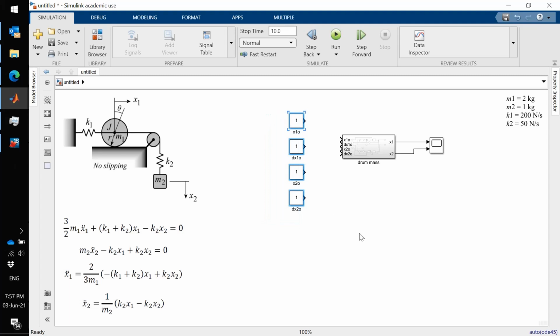You can select all blocks here, press Control button and hold, and then click on the target block, and the lines will be automatically connected in the same sequence. Make sure that the blocks here are arranged in the same sequence as the ports on the subsystem.